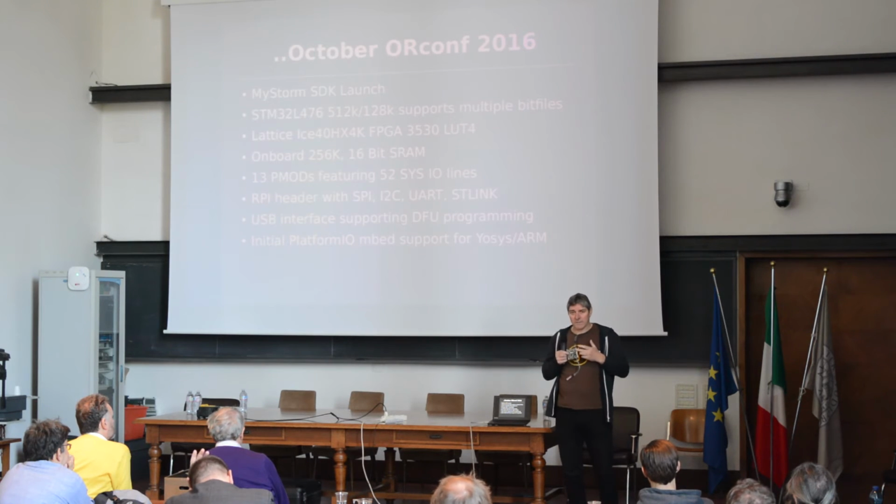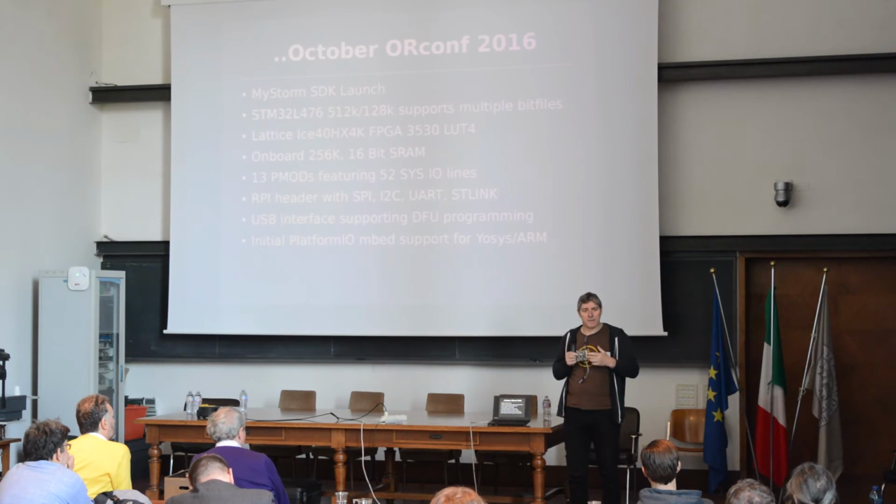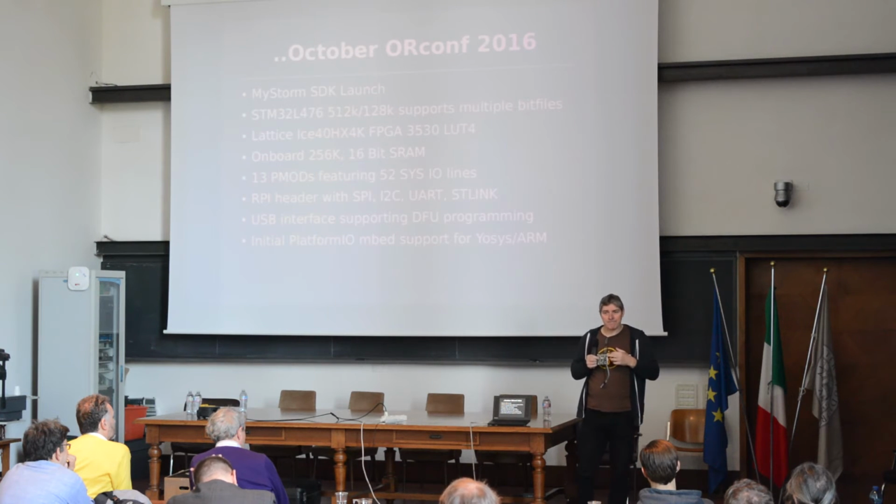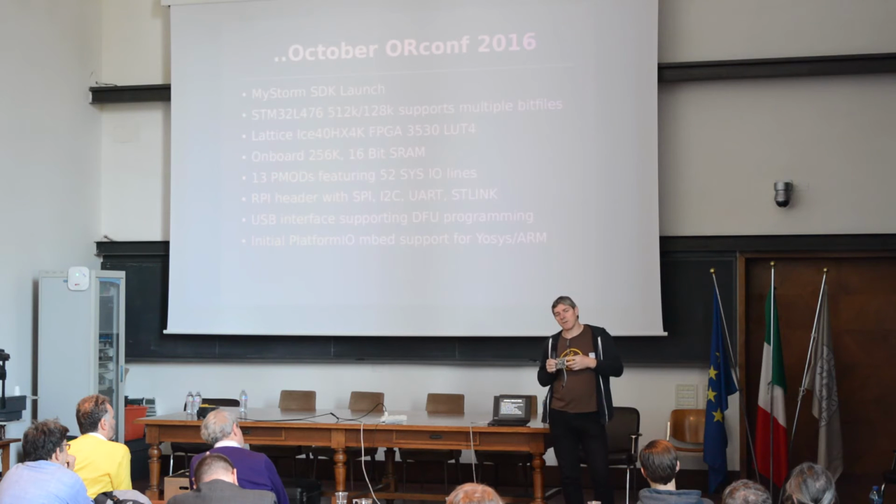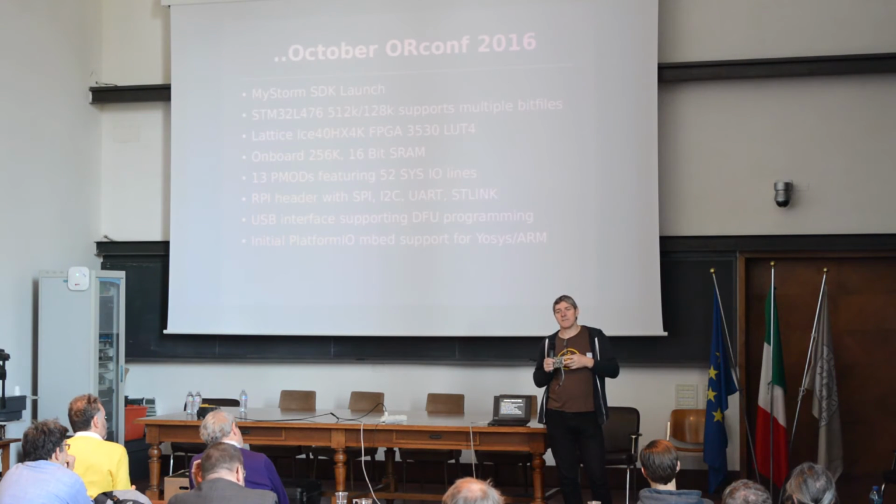Additionally, this header on this side here is a Raspberry Pi compatible header. The reason we did that is because initially we were using the Raspberry Pis as a means of programming, and we figured it would be good to make the Raspberry Pi connection as well. That enables you to program the entire thing from the Raspberry Pi. The way that it does that is it uses the UART bootloader in the 476 or the STM32103 to actually transfer the bit file.